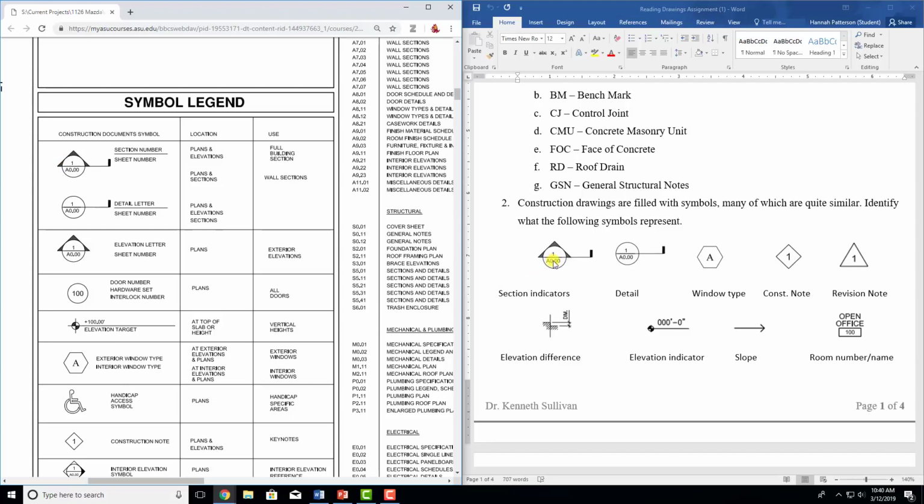We're going to get into that in a little while, but when you see that on a plan, this little section right here is going to be much longer. It's going to essentially splice a building. Going through the PowerPoint, I mentioned the different sections, and that's how you know if something is a section number. This top number will tell you what section it is, and the bottom number will tell you what page to find that cross section on. It's almost identical to a detail, except a detail doesn't have that arrow. The detail is the next one, and it's right here.